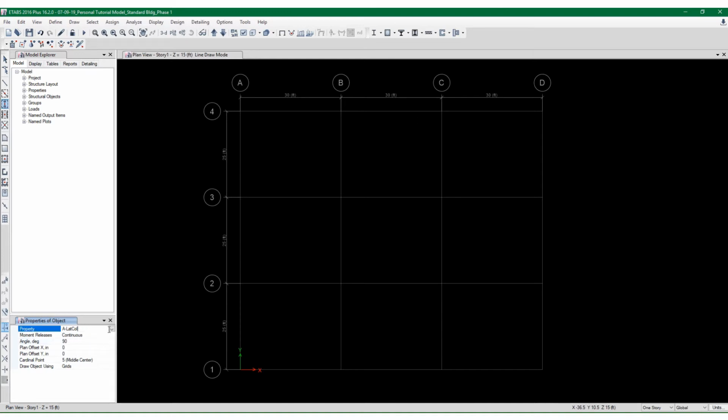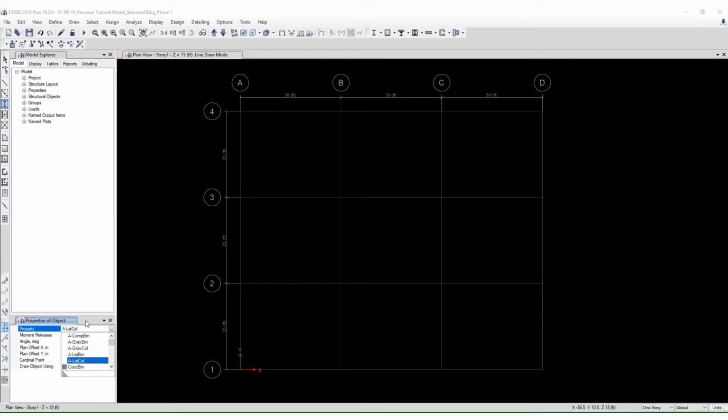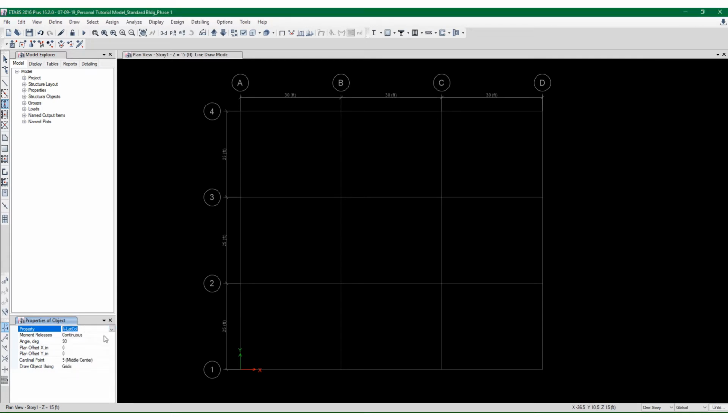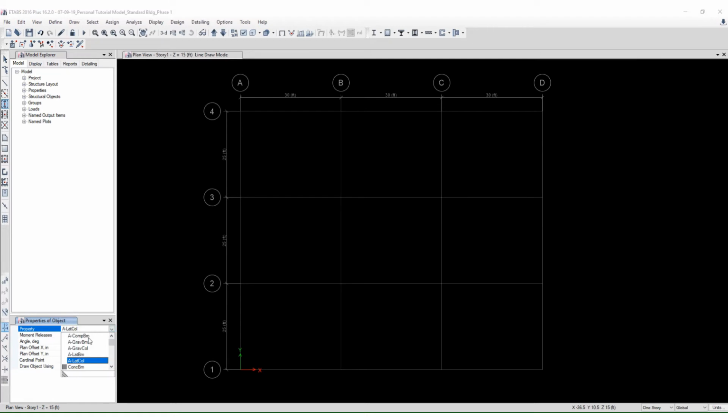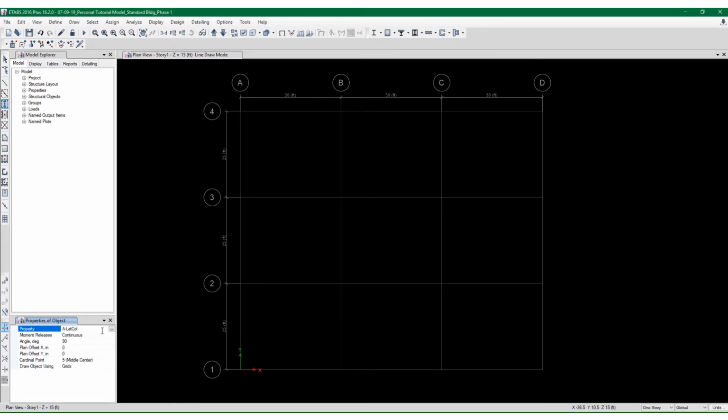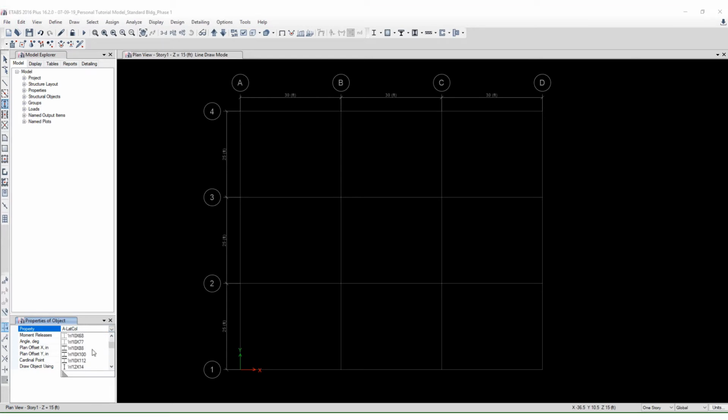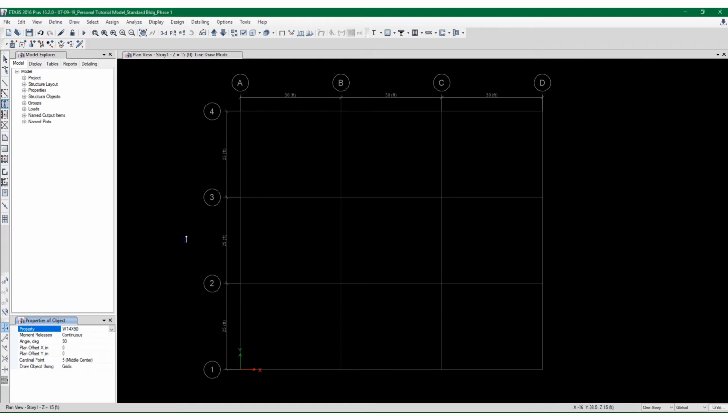Now the property that I'm going to use here should be selected as my W shape. If it's just a lateral column, that's actually a generic name that's used for lateral columns, and it might have some preset lateral columns that are available within, like a group, available for selection by the computer. But we will use 14 by 90s, just like we did in RAM. 14 by 90s. All right, so now we're good to go, and we can start drawing our column.